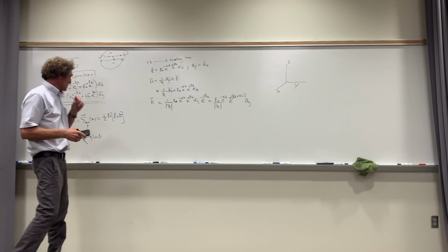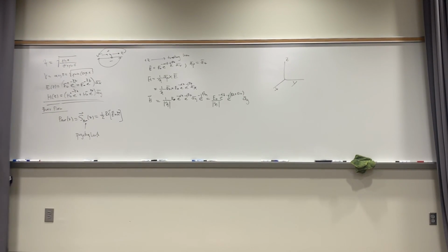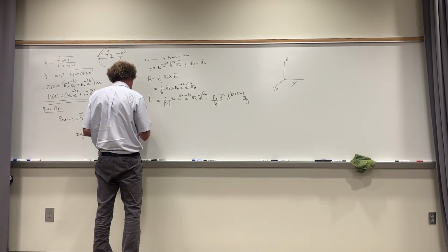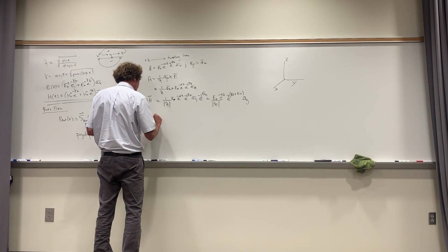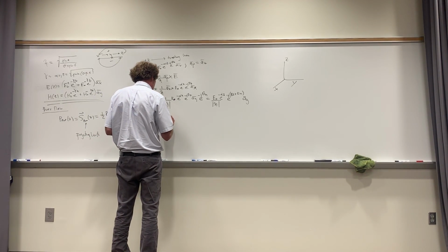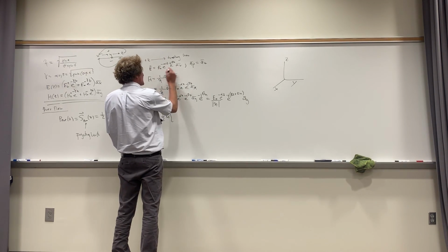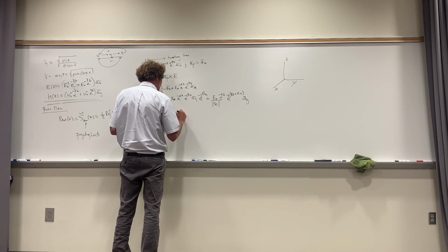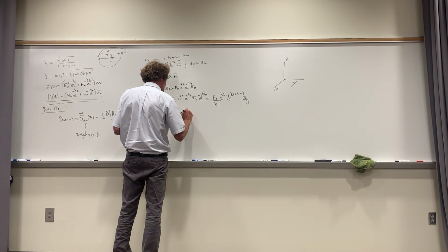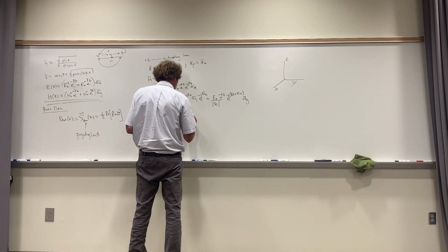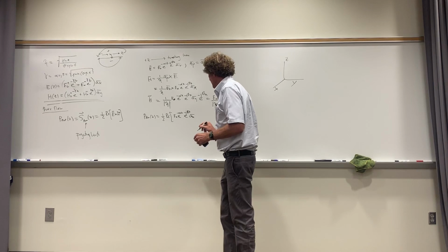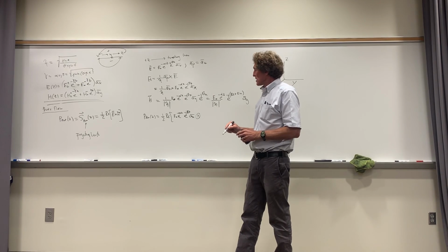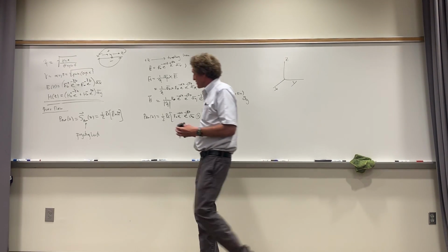Now we're going to go get the power. This is the power. This is an important one. This is the power for a wave going in the positive z direction. So the average power as a function of z is 1/2 the real part of the E field. That's the E field here. So it's going to be E naught, right, times e to the minus alpha z times e to the minus j beta z, ax. Just recopy that. And then it's crossed. I'm going to circle that. That's a cross.